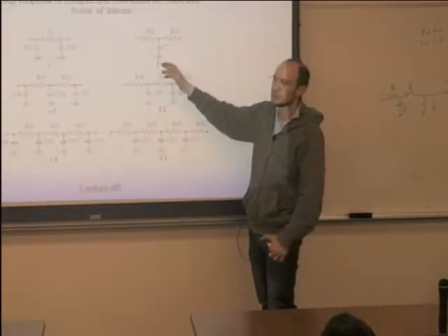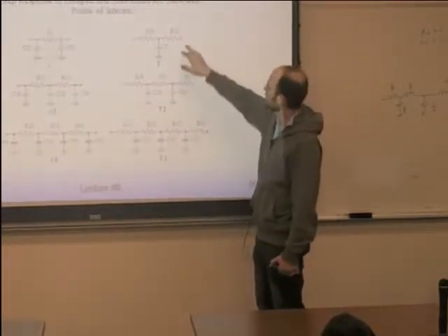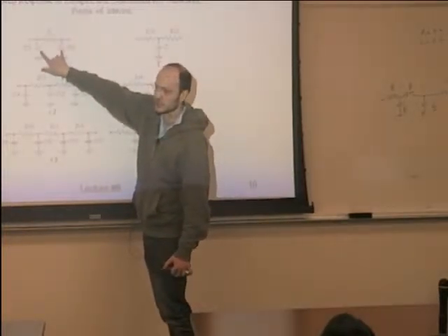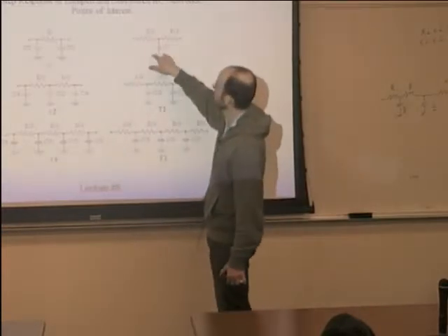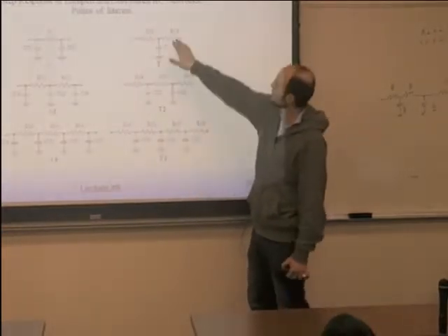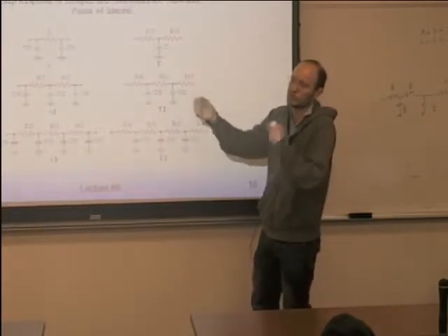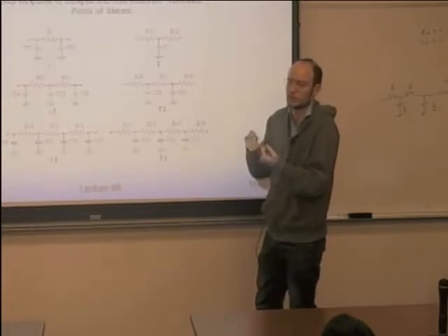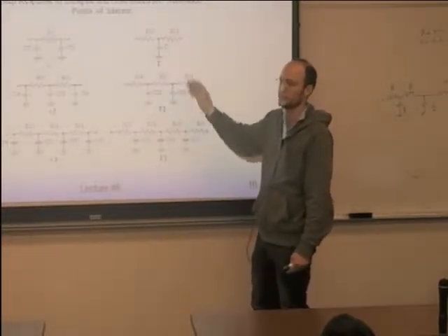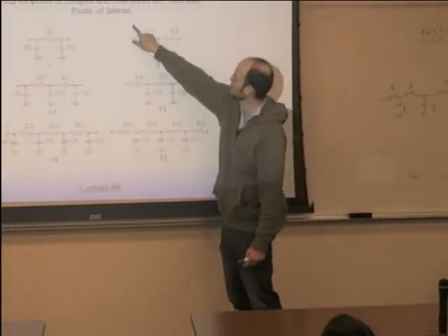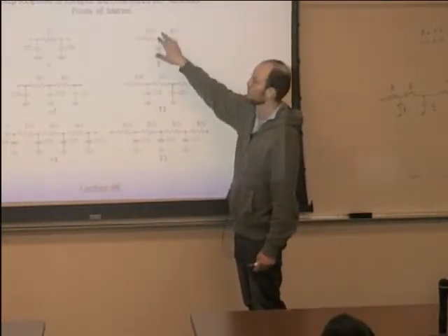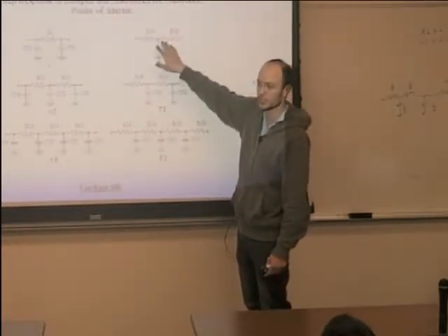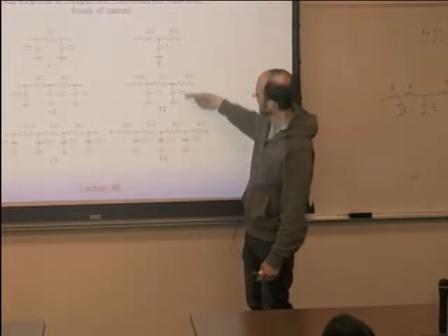The difference between these two is small. In this case, you break the capacitance into 2 pieces and put just 1 resistor. In this case, you put 2 resistors and 1 capacitor. Notice that they're all symmetric. You should try to do this always, because the wire, if you flip it 180 degrees, doesn't know that, so the model should be symmetric. These networks are all symmetric from left to right. So this will model a wire that goes from here to here. Presumably, as you use more sections of this network, you go from here to here.